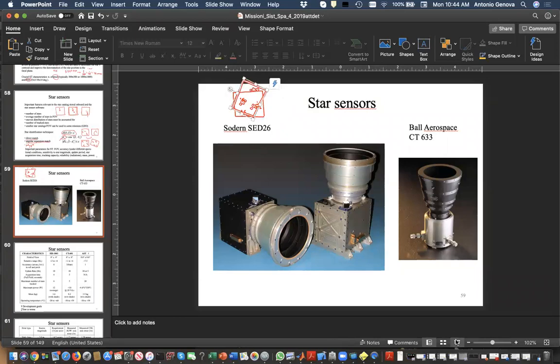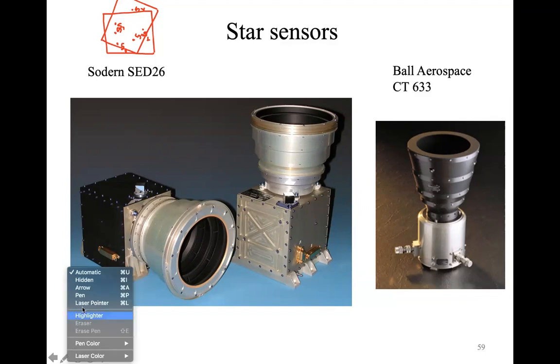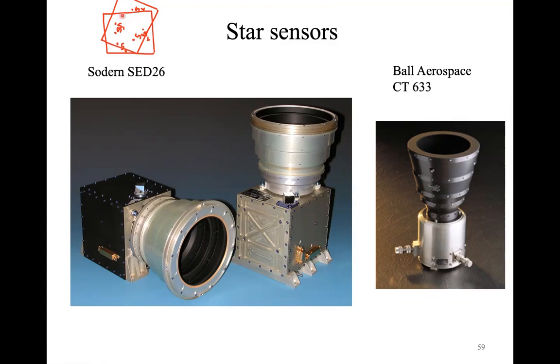What can happen is that at a certain time, one of the three stars can be outside your field of view. That, of course, can be a problem. So another important thing that the star tracker has to do during the star tracking mode is that when one star is exiting the field of view, it has to check in your CCD that another star is indeed within your field of view.